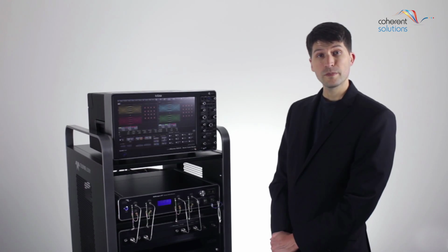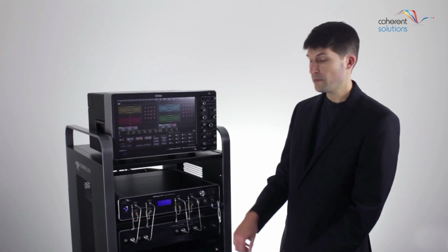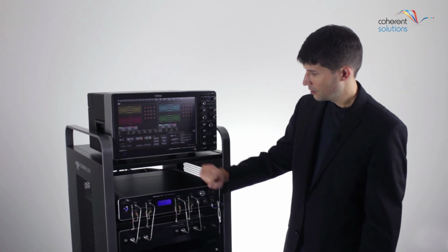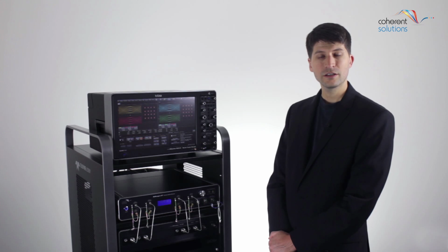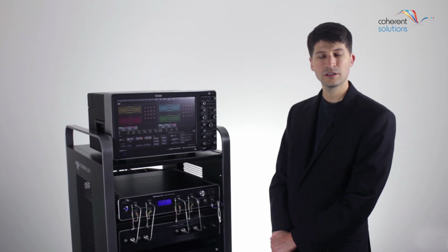So under the measurements section, you'll find the BER button. By enabling this functionality, you're accessing the true bit error ratio counting capability within the optical link. So this converts the detected modulation format into the various binary streams contained within your modulation format.